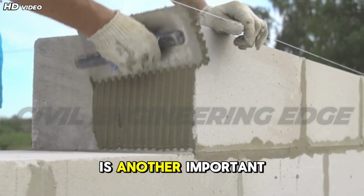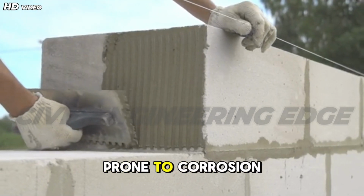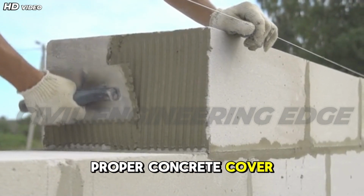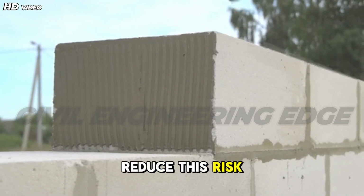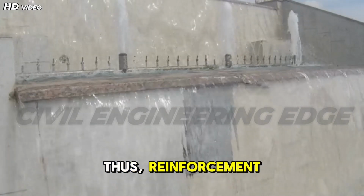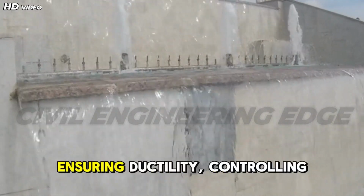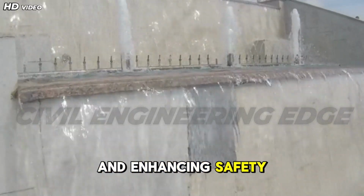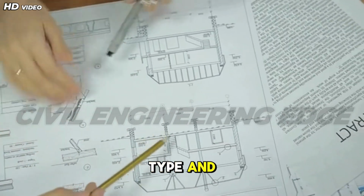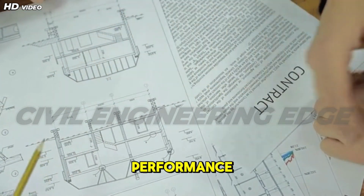Corrosion resistance is another important consideration. Although steel is prone to corrosion, proper concrete cover and quality concrete significantly reduce this risk. Thus, reinforcement bars are indispensable in resisting tensile forces, ensuring ductility, controlling cracks, and enhancing safety. Selecting the right type and detailing it properly is essential for effective column performance.